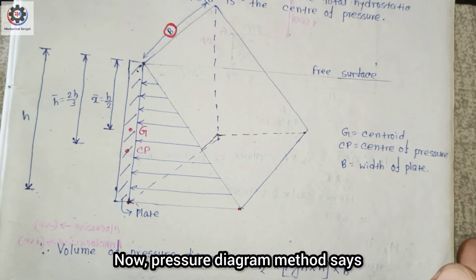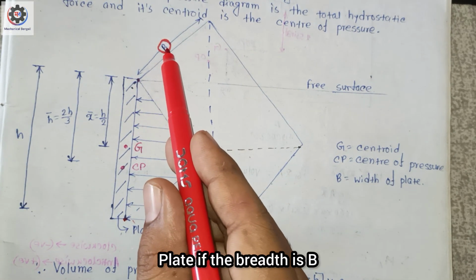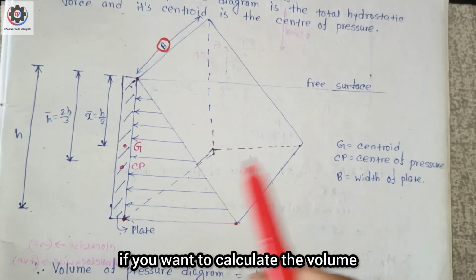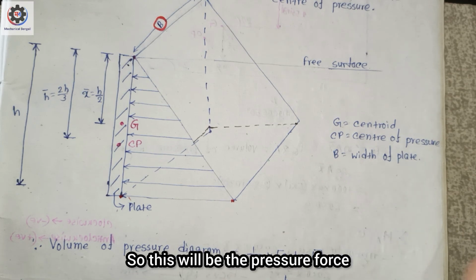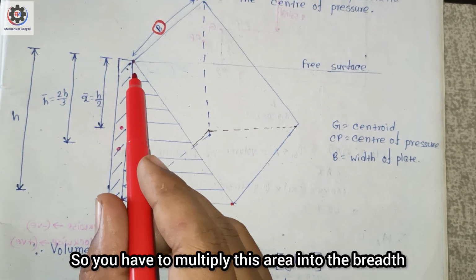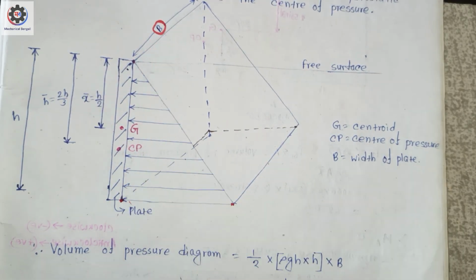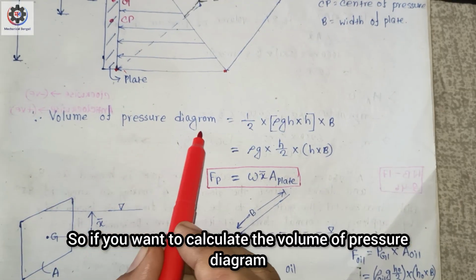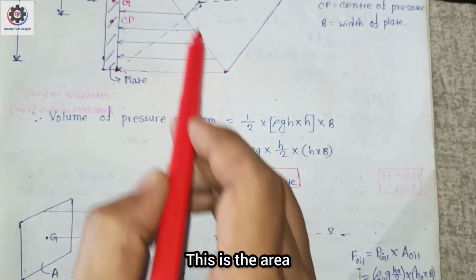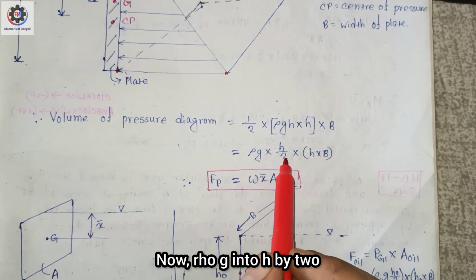Now the pressure diagram method says that perpendicular to this plate, if the breadth is b, going inside the paper up to this point, the volume is the volume of the pressure diagram. This will be the pressure force. To calculate the volume, you have to multiply this area by the breadth or width of the plate. So the volume of the pressure diagram is half into rho g h into h, the area, multiplied by b to get the volume. That is rho g into h by 2 into h into b.